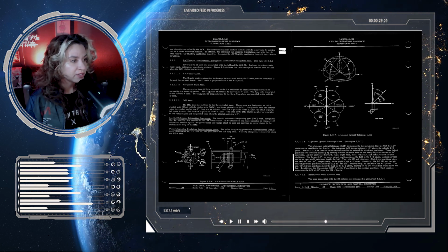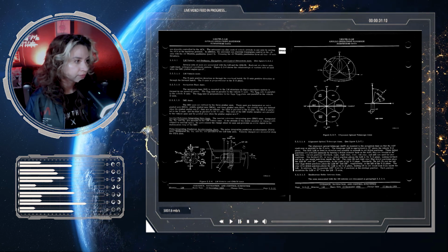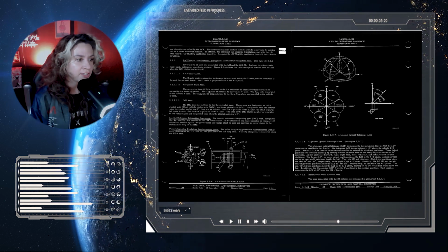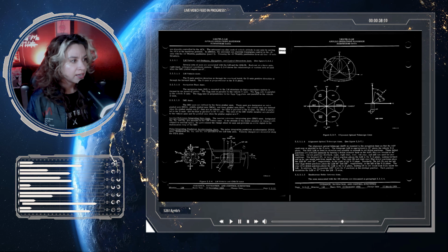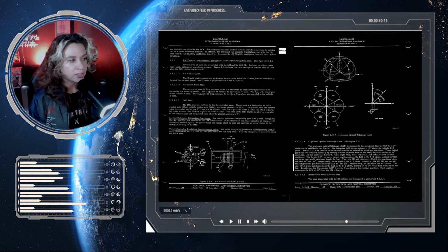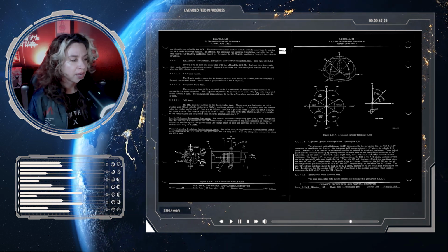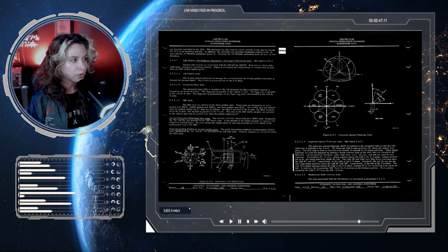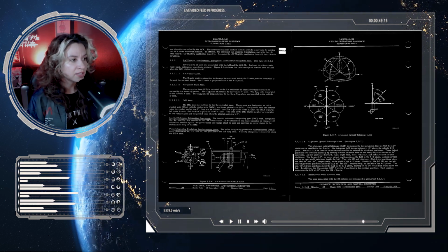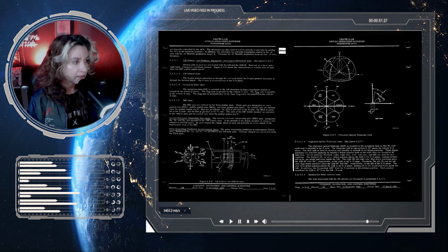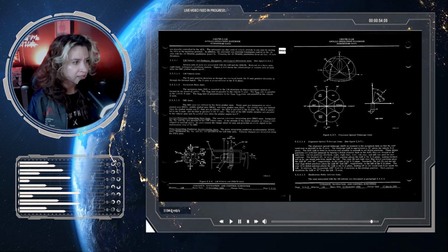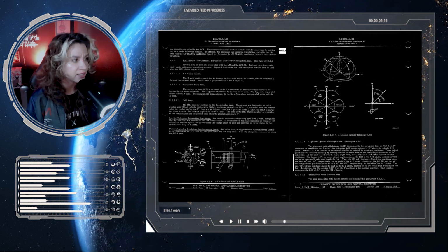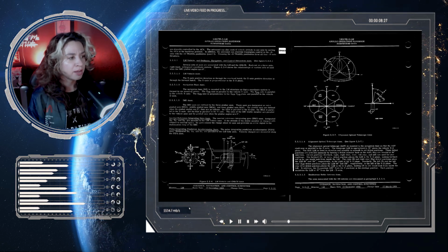The inertial reference integrating gyro, or the IRIG, axes are designated XG, YG, and ZG, and are parallel to the LM vehicle axes. If the attitude of the stable member is changed with respect to inertial space, the gyro senses the change about its axis and provides an error signal to the stabilization loop of the IMU.